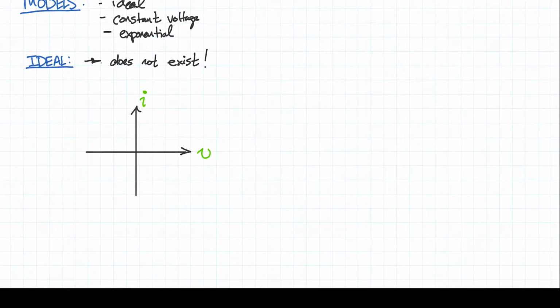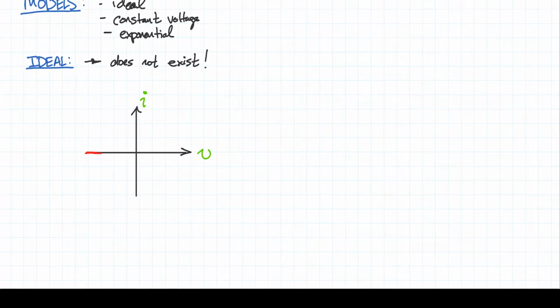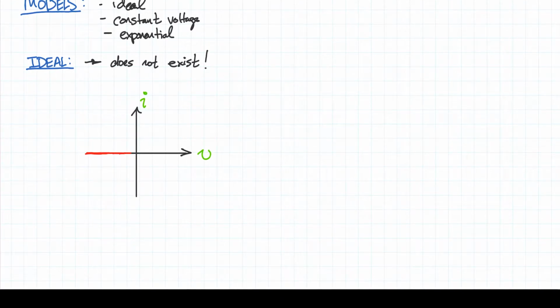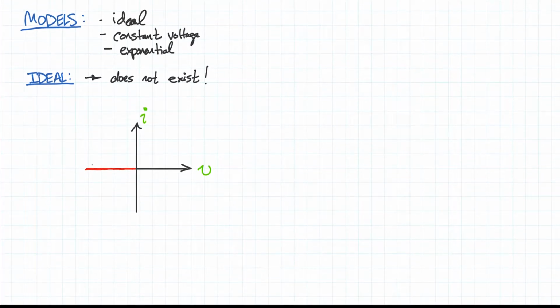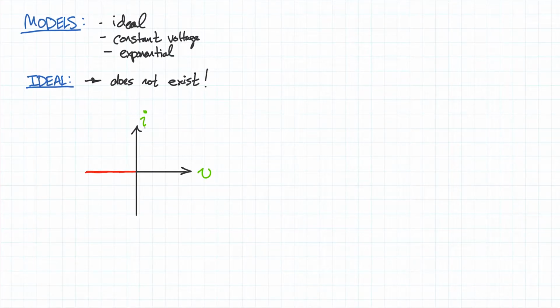And so for an ideal diode, the diode current for negative voltage is 0, and then when V equals 0 at this point, the current is going to spike like this. Obviously this can't really happen, because if I were to extend this graph, it would go to infinity. You cannot have such an infinite current, but basically it becomes a short circuit, and then the current through the diode would be limited by the circuit around the diode.